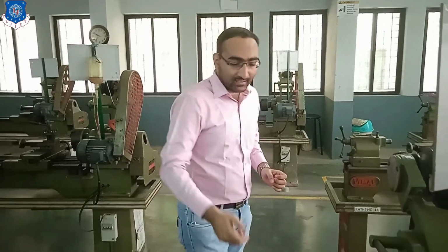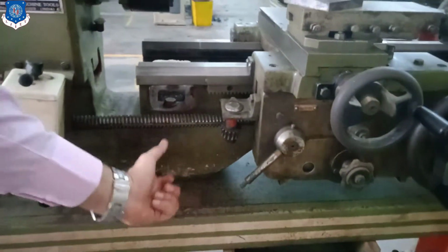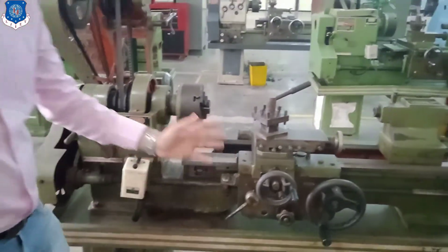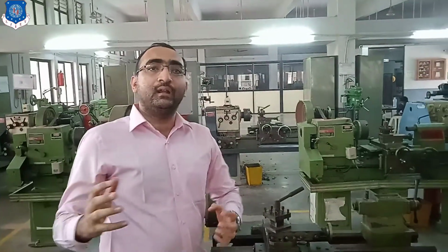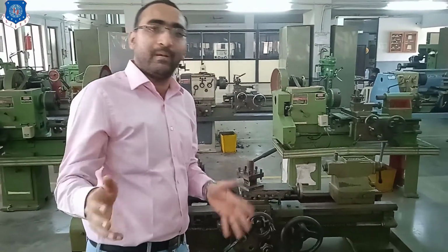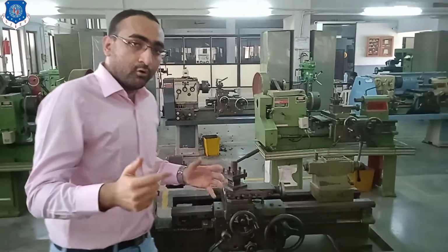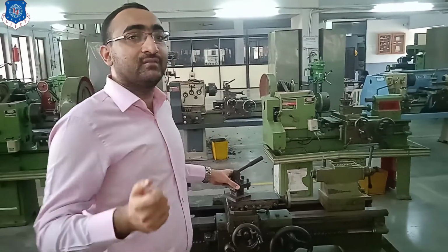Now the fifth is known as the lead screw. That is your lead screw. You can see the lead screw over here. For semi-automatic motion and for threading purposes, we will be using this lead screw. Now we will see how we can move, because we know that your workpiece will only move in a particular fixed path. It will not move in a to and fro direction. It will move on a particular point only. So for that reason, we will be moving our tool for the cutting action, as we have seen in our principle.